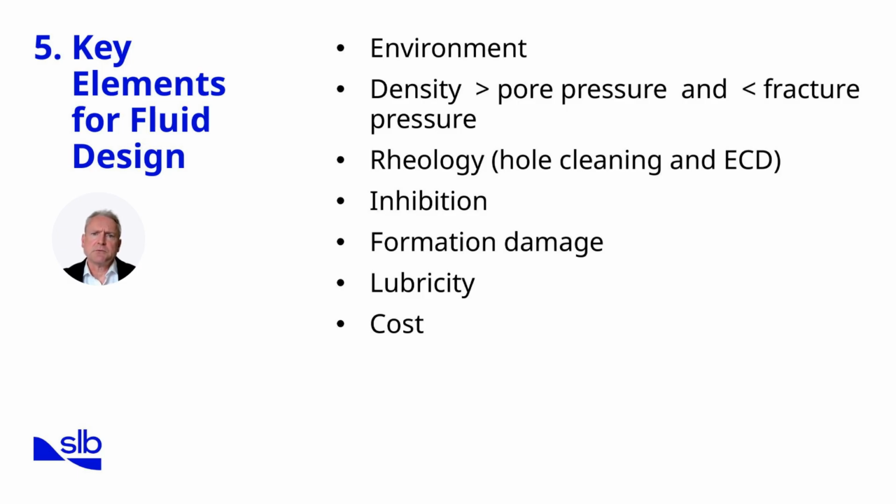We also focus on minimizing formation damage. Incorrect fluid chemistry can reduce reservoir permeability and impair productivity. Lubricity is another factor, especially in extended reach wells, where torque and drag can become limiting. Finally, all of these requirements must be balanced against cost, as fluid systems are a major contributor to well expenditure.